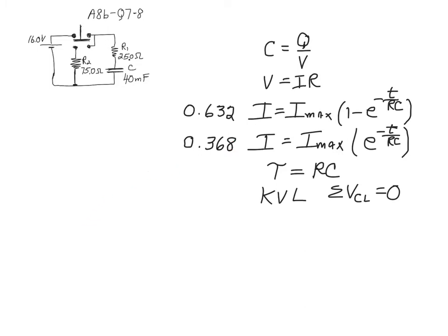During the charging cycle, after one time constant of time has gone by, the current or the voltage or the charge as it's charging will have reached about 63% of its final value. And that behavior continues throughout. During the next time constant, whatever's remaining will go 63%, and then whatever's remaining left will go 63%. So the behavior ends up being that during the first time constant it's about 63%, then something like 86%, and then 95%.